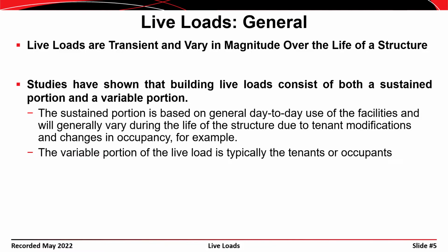But it's important to note, too, that things can change over the life of the structure. So one thing to bear in mind is you might want to design not just for the load that you think is going to be in the structure right after it's opened, but maybe give some thought to designing the structure for what it might possibly be used for in the future. And also bear in mind that live loads can include high magnitude events, things like if you have a renovation or remodeling of the structure during its life, then you might see a load in a structure that is higher than what you would consider for your day-to-day use, but would also be considered part of the live load.